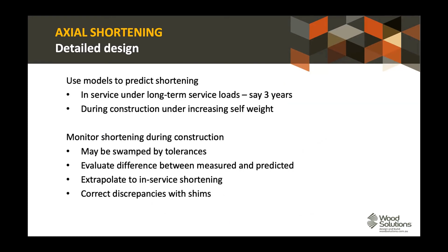So we need to understand the shortening, and we also need to review and monitor building movements during construction for some of the larger scale timber buildings that have been built, such as Brock Commons, for example. Movements were predicted, details were developed to accommodate those, and then during construction they were monitored and discrepancies from the predicted were dealt with using shims and modifications as we go.